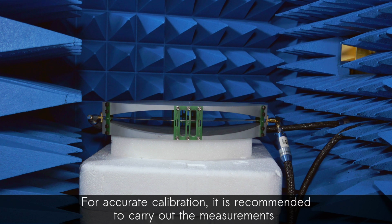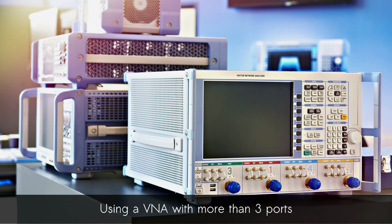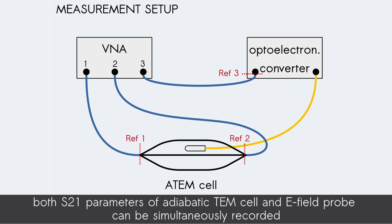For accurate calibration, it is recommended to carry out the measurements with both TEM cell and E-field probe in a small anechoic chamber. Using a VNA with more than 3 ports, both S21 parameters of the adiabatic TEM cell and E-field probe can be simultaneously recorded.